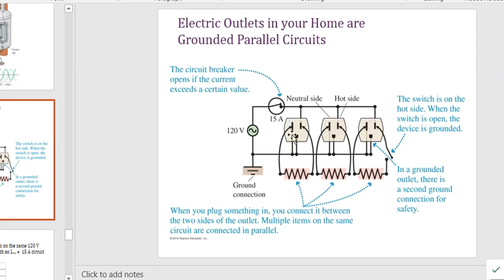And maybe part of how you can remember this is that the smaller one is too small for a kid to stick their finger into there. And so they would not get shocked if they actually managed somehow to get their finger into the larger one. So the smaller one is the so-called hot side. Just a little mnemonic to remember it.